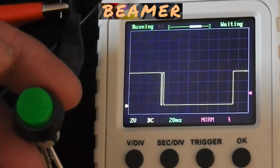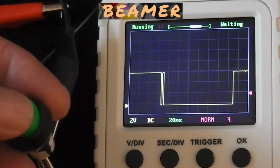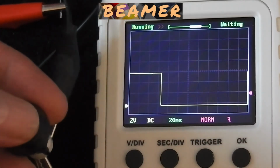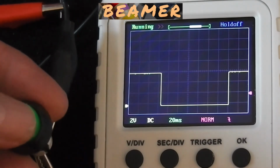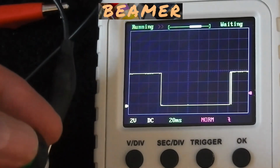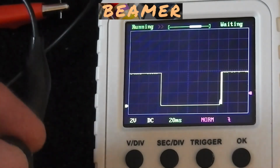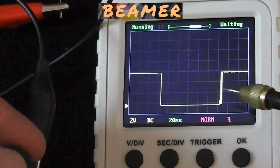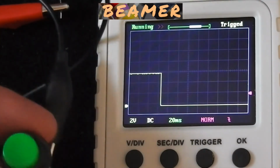So this is a close-up of the DSO scope and my switch, and I'll push it again, and that's the next one. You can see it's a perfectly clean signal, and again, and again, and again. You can see that there is a bit of bounce going on at the rising edge there. Clean, clean, clean, clean. And there we are.